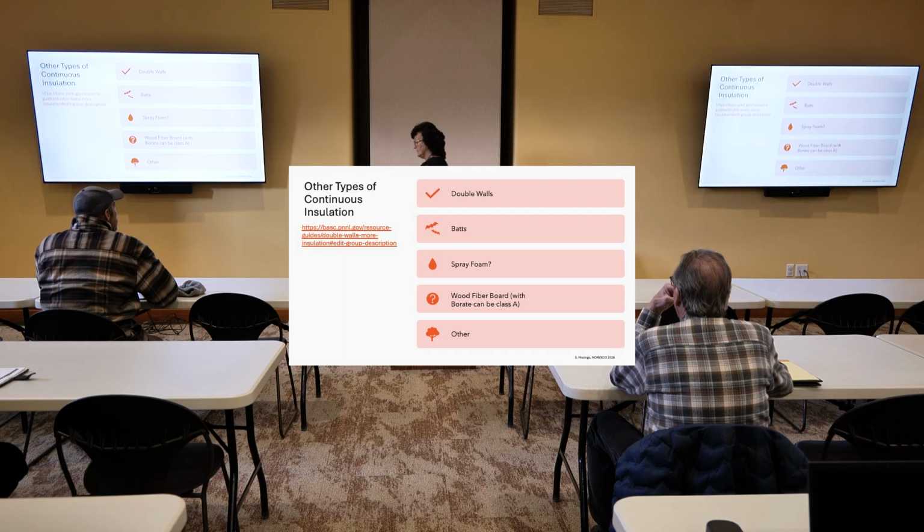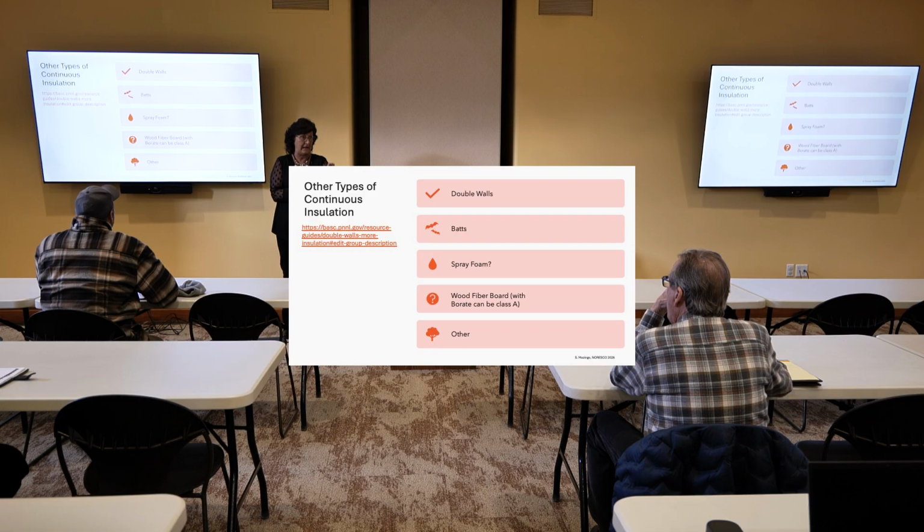I've seen people build a structural wall and do all your cavity insulation in it, and then go over it with a rock wool or something on the inside of that, and then build a small wall on the inside for your plumbing and your electrical that has no insulation. All your insulation is there, but you have a cavity and a continuous, then an airspace and a barrier, and then you have a little wall that handles all your plumbing and mechanical stuff.